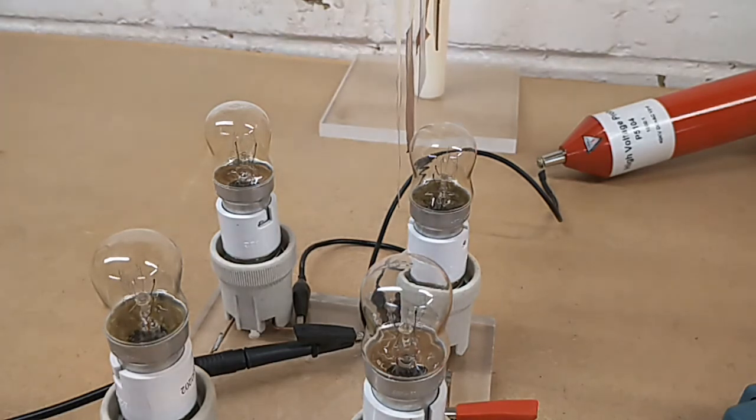So we're going to take a look at that now, but if we think about all of that energy from the spark gap spread out in a broad band, there is only a very narrow tuning range of frequencies with which we can actually transfer electric power from the generator at very low loss to the final receiver load. So in a way, we're only coupling a small amount of energy that is being stored in the transmitter tank capacitors. Just a small amount of that energy is ever going to reach the load on the output of the receiver, and hence that's why they just don't light very brightly.